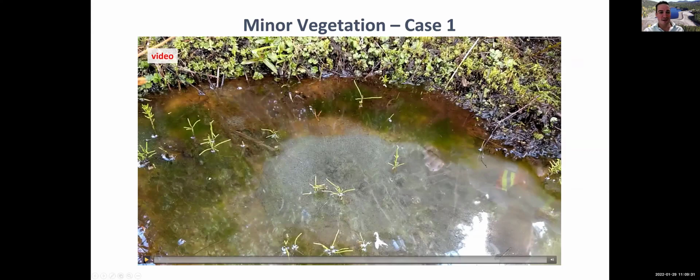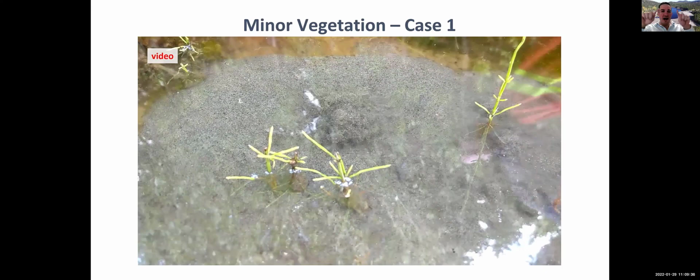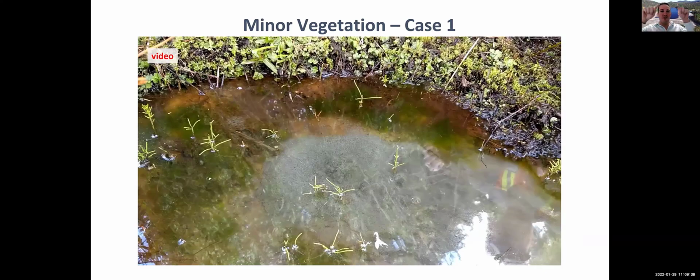I almost got low frame rate, but what it is, the water's coming up and it's actually flowing and creating a boil. So it could be pulling material from out of the foundation, or maybe it's just moving water right at the exit. But the whole toe area has quite a bit of seepage. And here we see that it's gotten to a point at which that seepage is able to start to erode that toe, almost like a backward erosion. It starts from downstream to upstream, like a pipe. It starts to erode a pipe and then the water finds it.